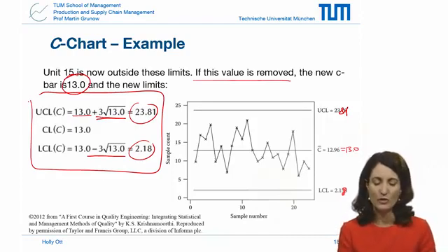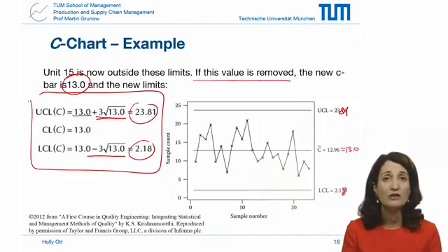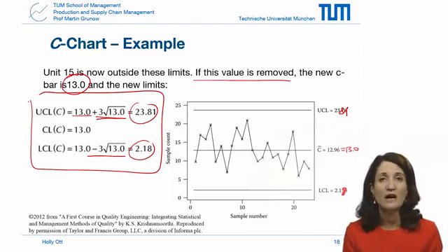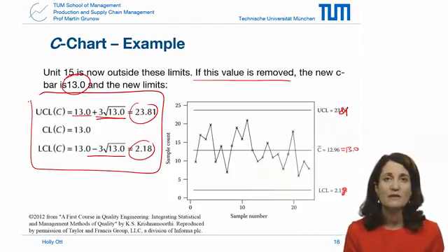And we just want to note the method of calculating control limits for the future by using the remaining data. So we had 25 points, and we ended up only using, in this example, 23 points. This is recommended because often if you take a whole new sample set, it's expensive and time consuming. So if the process is not so badly out of control, and you can find the assignable causes and remove them, then it's probably not a bad idea to use these remaining data.